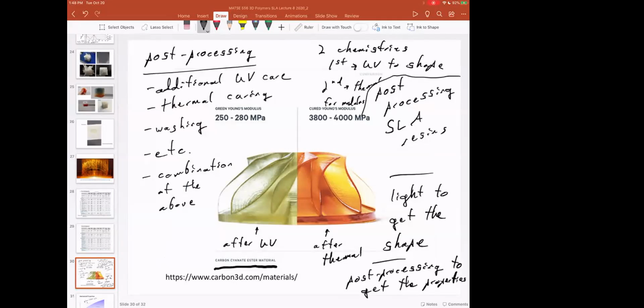And really this idea of post-curing, or what we do to the SLA part after we do the acrylate photopolymerization, is something that's interesting for making finished parts that are not prototyping parts and don't have high enough strength, but to produce finished, in this case automotive grade or electronic grade materials, which is what cyanoacrylates are used for. That's of interest to people with SLA.